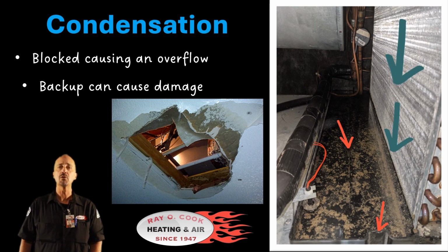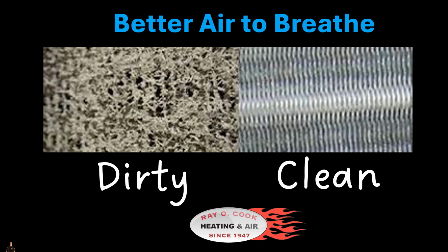Keeping your indoor coil clean helps eliminate the chance of condensate water causing you a great deal of grief down the road. Finally, the air that we breathe in our home travels through your indoor coil. The cleaner your indoor coil is, the less chance of particles mixing with condensate water, which can cause forms of bacteria to grow. This can be a source of breathing issues in some homes.